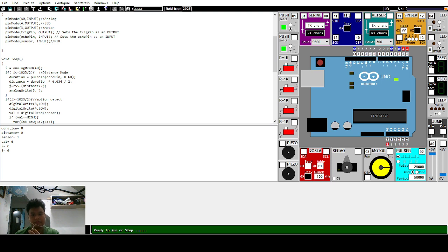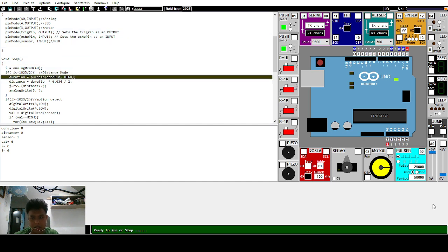So let us compile, accept, and this for pin number 1, which is the push, it is a PIR, so it will basically just detect. So if it's high, it detects motion, and if it's low, it does not detect motion. So let us set it to no. And A0 is the analog input, and pulse is the ultrasonic sensor. So it's in pulse. So let us test it.